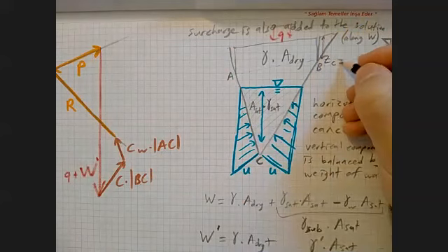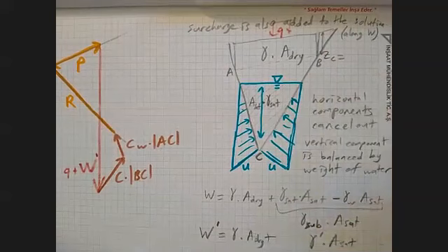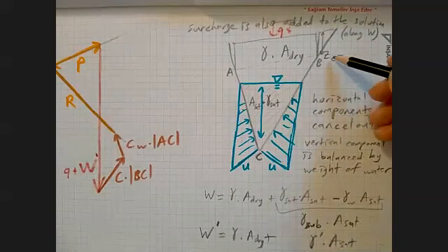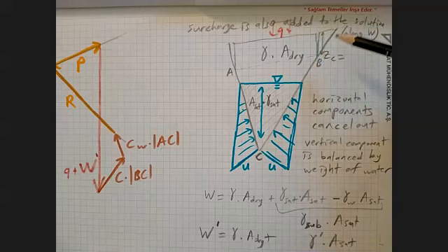So how do we get ZC? Of course, as I said, we are modifying Coulomb's wedge analysis here by things we know after Coulomb. So after Rankine, we know how to do this. And if you remember, it is equate the horizontal active stress to 0.